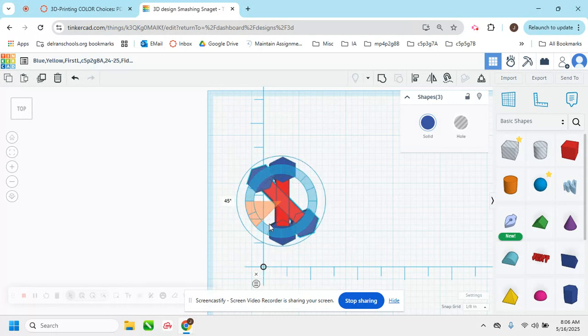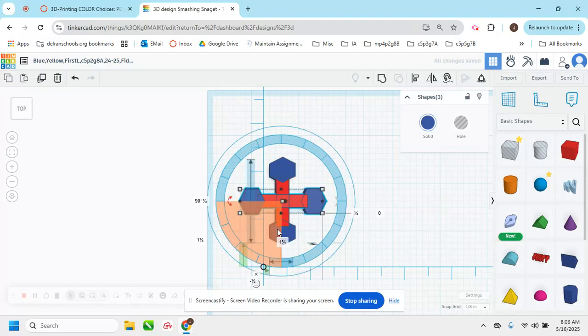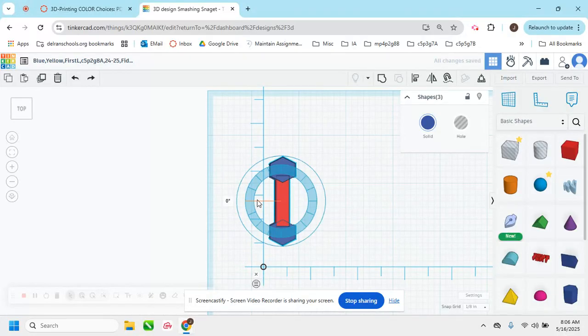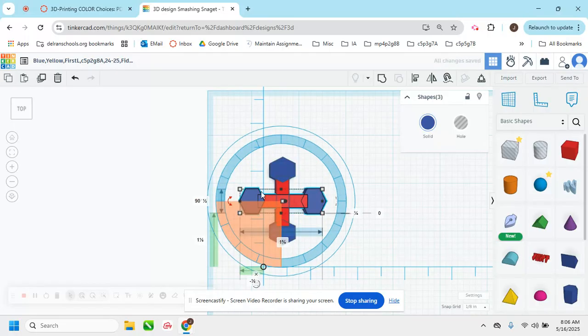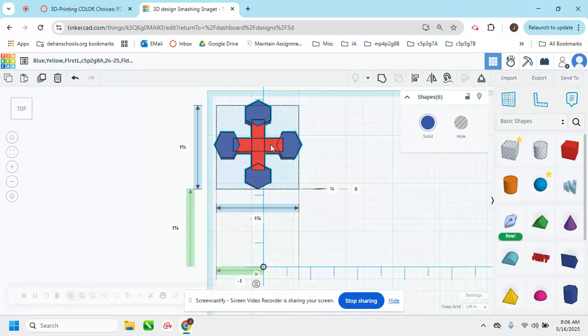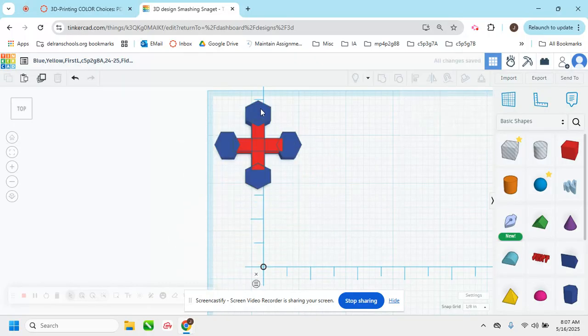We can do it by hand, rotate 90 degrees like that, or we can do it by clicking here on the rotate tool and then typing our angle in. Okay? Now, that's the easiest fidget spinner to make. You can add text on these spokes, other decorations, things like that. We'll add the bearing to the center.